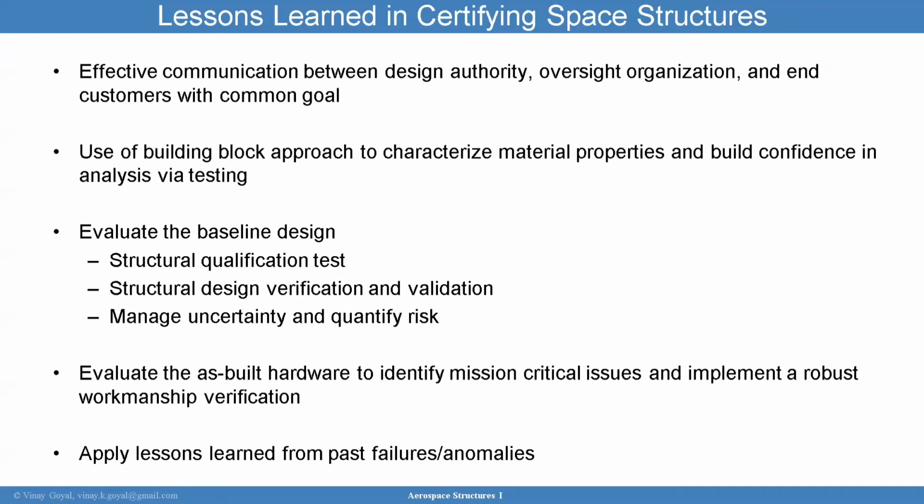Evaluating the baseline design also means making sure they've performed a structural design verification and validation, and that they're managing uncertainty quantification and risk. So that means they're going to have uncertainty in certain material properties, uncertainty in certain loads or something like that. And then you can use the analysis that has been anchored to study the sensitivity to those uncertainties.